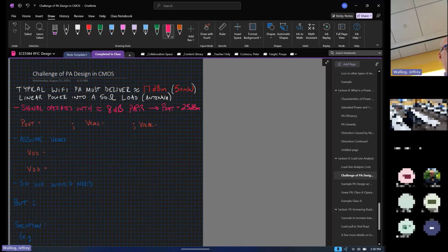All right, so for a Class A amplifier, or even a Class B amplifier, the output power is equal to the RMS voltage squared divided by the optimum termination resistance. So this is that load that we put directly at the drain of the power amplifier. We're probably going to do that using a 50 ohm load in a matching network ultimately, but this is what we present right to the drain of the transistor.